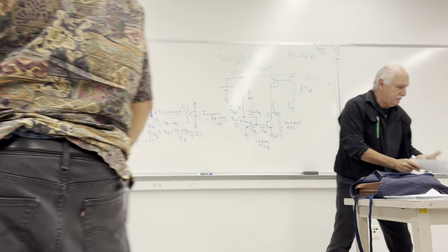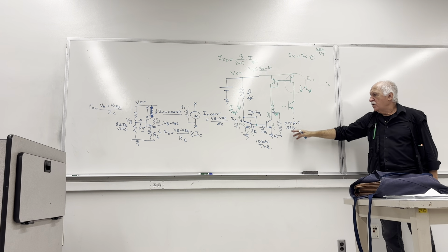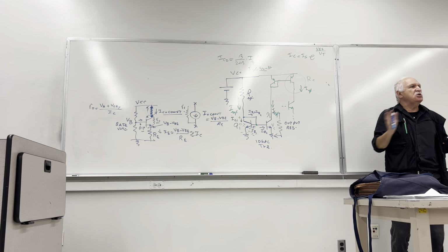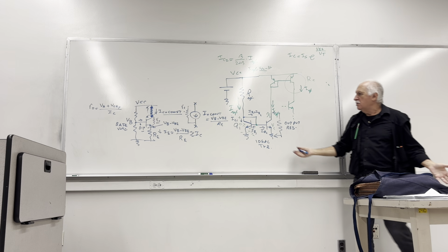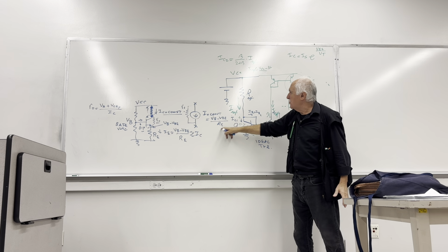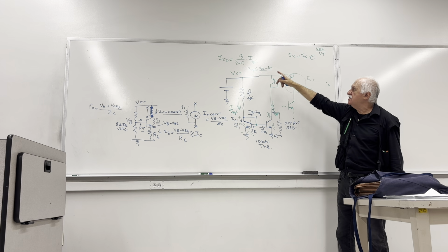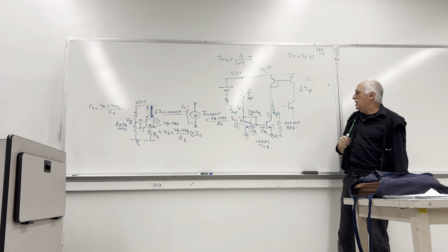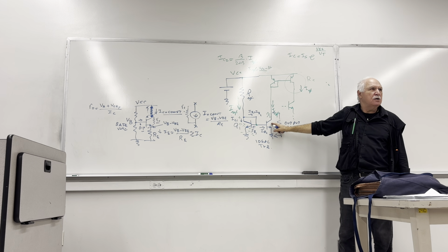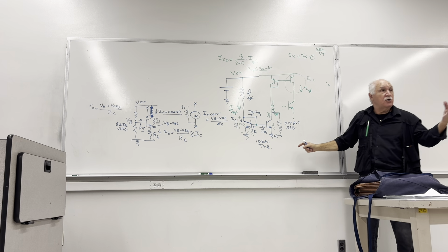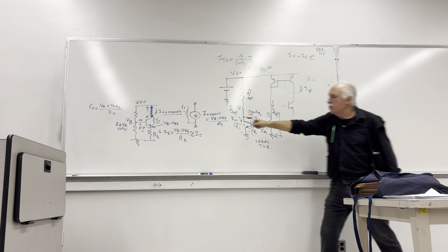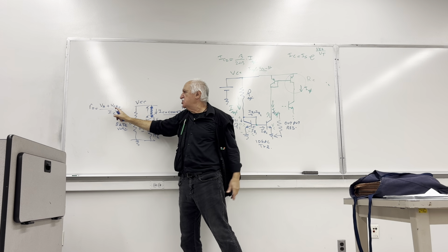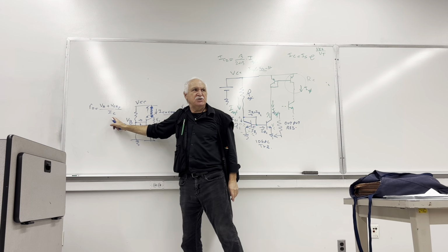You have it? Okay. So, in order to see what the dynamic resistance will be, after we know all about the DC conditions, how do we know? I just calculated here, gave you a formula with values and data. You can predict the current here, that would be your IC. Then you need the VA of this transistor, the early voltage, and RO is VA plus VCE quiescent of that transistor, divided by IC.